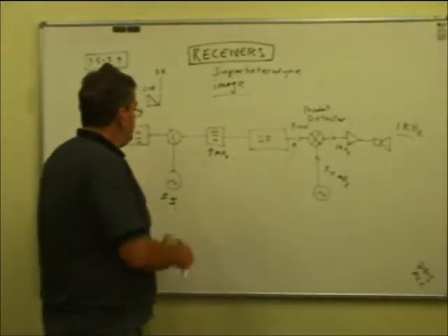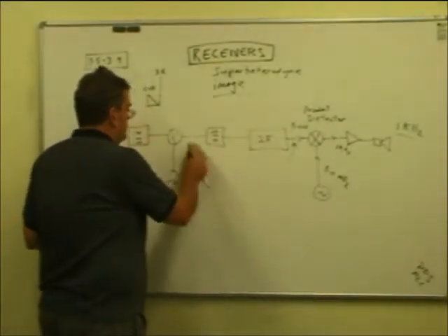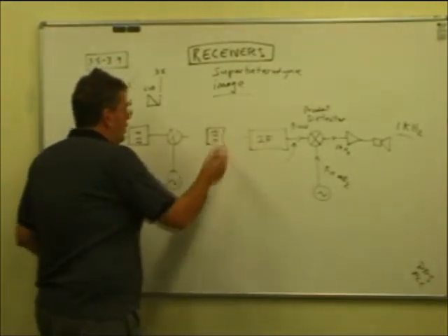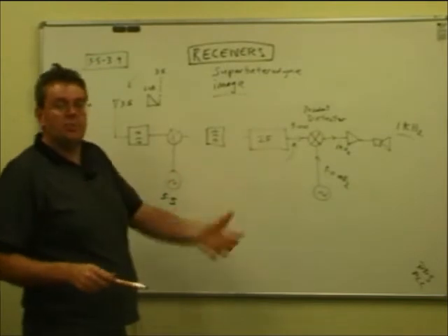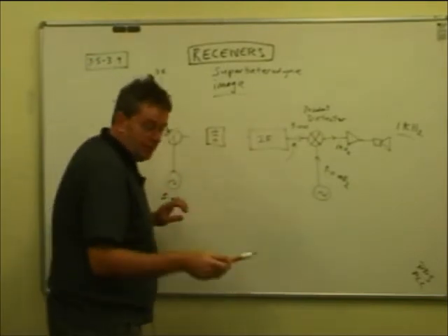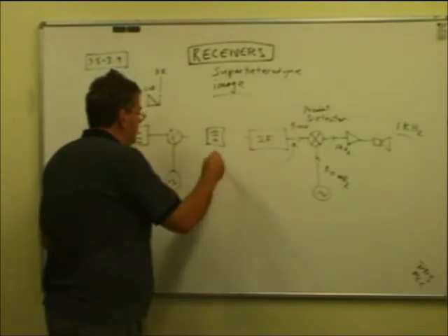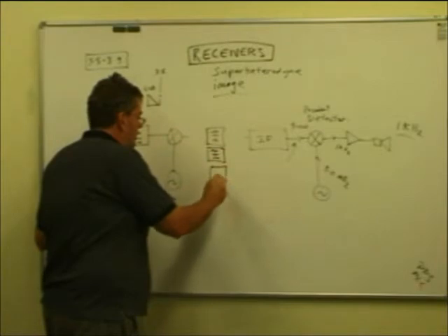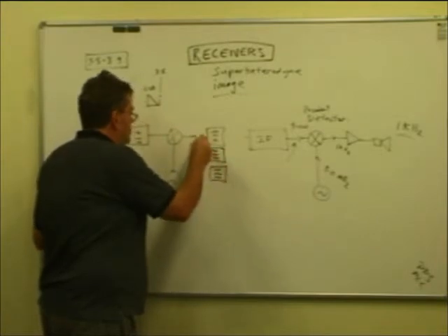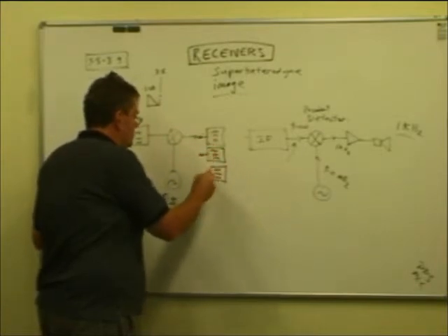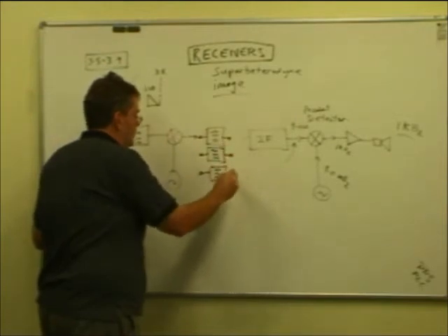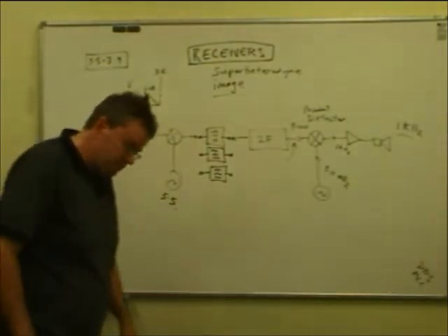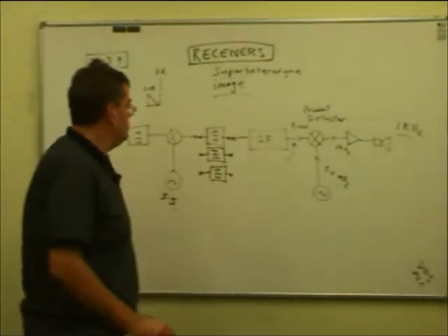So what's typically done in receivers is these filters are switched. So there'll be a bank of filters. Often if you buy the lower specification you'll just get one, but you can get them added in as optional extras. That one I showed you before, the AC one there, I've got a Morse code filter in that, for those of us that still use it occasionally. So often what you'll have is a switched arrangement there. A symbol shows us that these can be switched in and out. And the receiver, according to how you operate it, will select the appropriate filter you want.